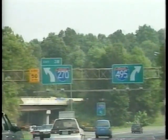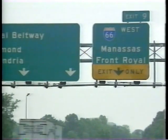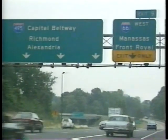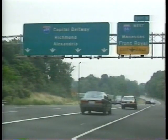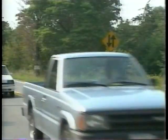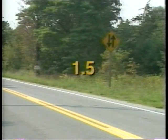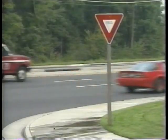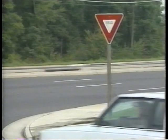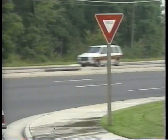In addition to these general rules, there are standard principles that govern all placement and location. They include overhead installations. This kind of installation is reserved for situations where the driver's view is obstructed and for freeway lane control. Sign height practice. Sign height in rural areas is usually 1.5 meters to the bottom of the sign. Urban and freeway signs should be higher, about 2.1 meters.